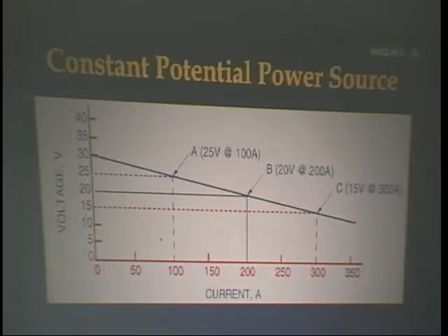On page 759, first column, highlight this. The volt-ampere curve of the constant voltage power source used for gas metal arc welding has a relatively flat output slope. Figure 2117b shows that. Small changes in the arc voltage result in relatively large changes in the welding current. Figure 2118 shows that when the arc length shortens slightly, a large increase in welding current occurs. This is a bullet. This increases the burn-off rate, which brings the arc length back to the desired level.